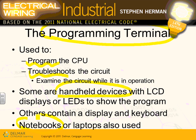You grab your laptop, plug it into the machine. You can look at the programming, load the program to the machine, to the PLCs, download the program, troubleshoot the machine, turn things on and off from your laptop. I don't know, Karen, if you guys were able to click, like S7200 has the capability, as you program it, you can click on close a contact and it will run the machine right from your laptop. I don't know if you guys did that with Scott or not. So you can run the equipment right from your laptop, in addition to troubleshooting it and programming.